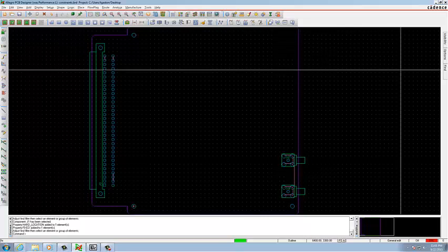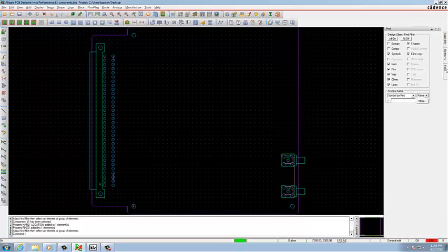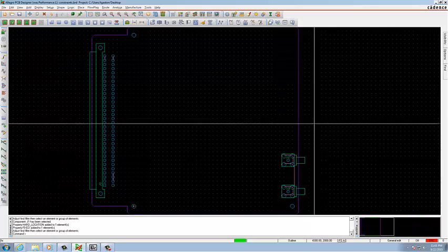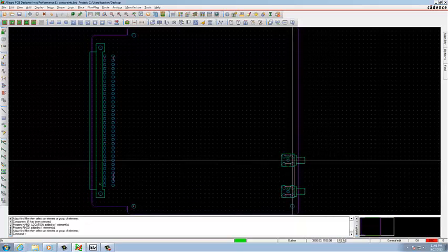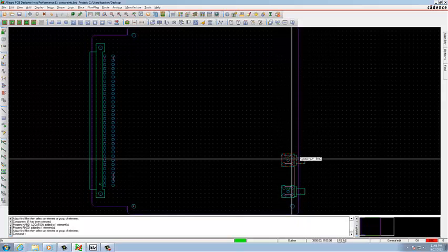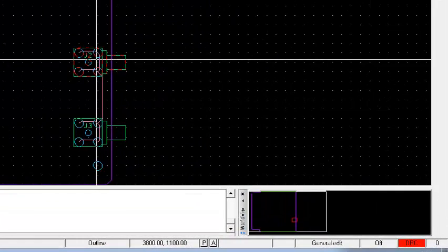Now we want to scroll over back to find again. Now here's the key here. Under design objects find filter, we want to click all off. Okay? And after that, the only thing we really want to turn on is the symbols. And now we want to click on both B and C connectors. So these guys right here too, if you're not familiar with the layout. I'll click one.